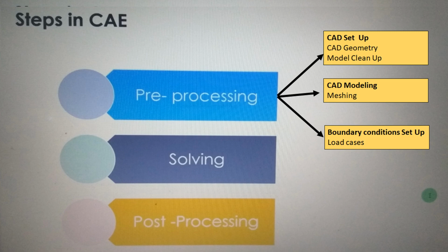We interpret the model in a particular form. So if this translation has some bug or issues, the CAD which you get as an input might have some geometric defects or quality defects. These defects, if not addressed, will carry till the end, and your final CAE model, the finite element model FEM, will also have these defects.